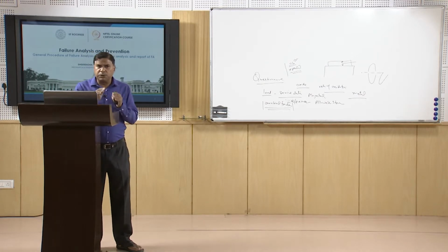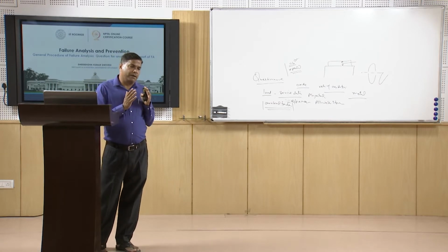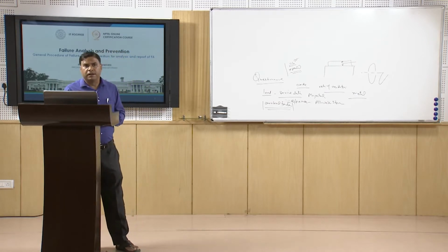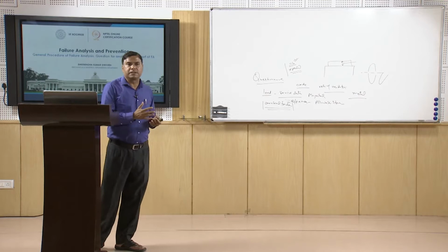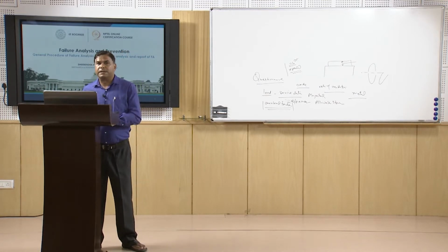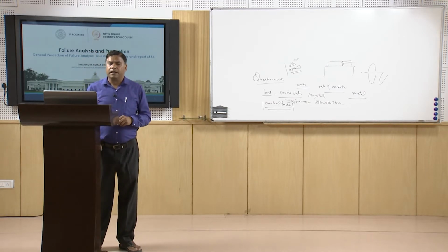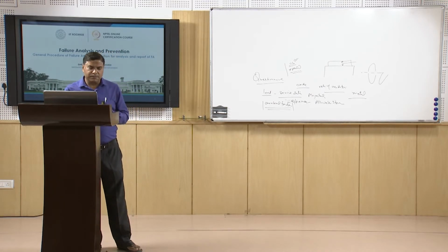Just by using the principles of the microscopy of the fracture surface, we can identify the kind of stresses which were there. Sometimes people speak as per their convenience to hide the information, but the microscopy of the fracture surface can indicate the kind of stresses under which the component has been exposed during the service and under which failure has taken place. Then determination of the fracture mechanism and/or the failure mechanism is also important.